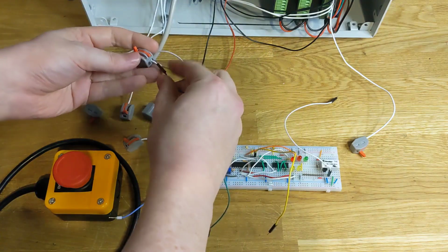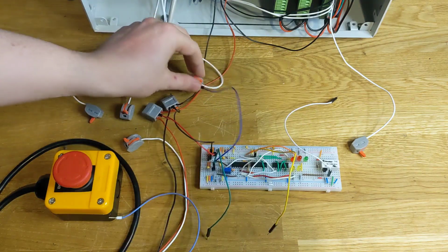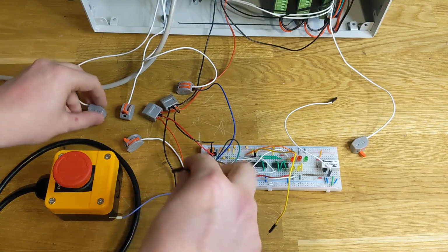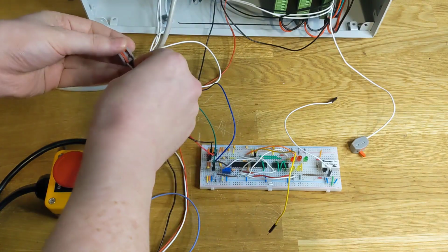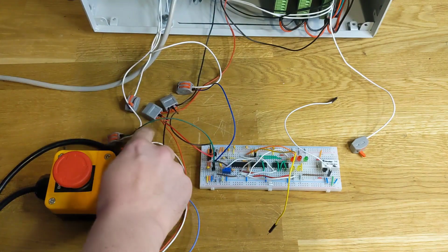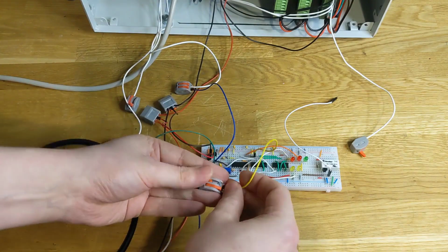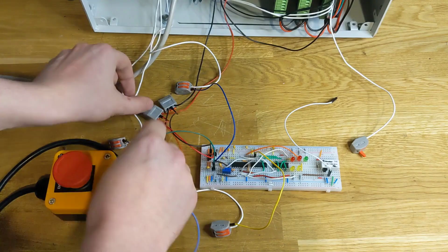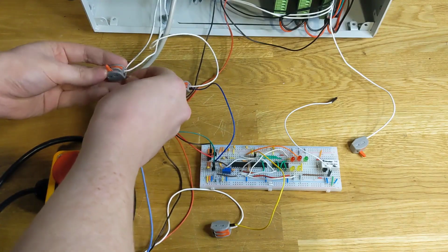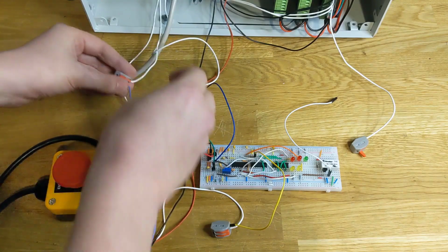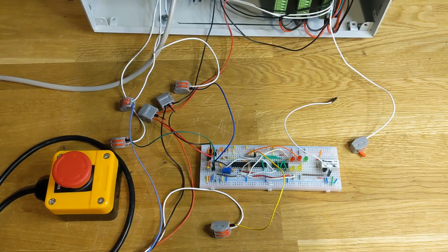This area detects the charge pump, so we'll connect that to the charge pump output here. The amplifier enabled output pin connects here. The normally closed pole of the emergency stop switch is connected to the safety module, and the normally open pole of the emergency stop switch goes to the e-stop input parallel port pin. This way LinuxCNC sees the e-stop event at the same time as the safety module.